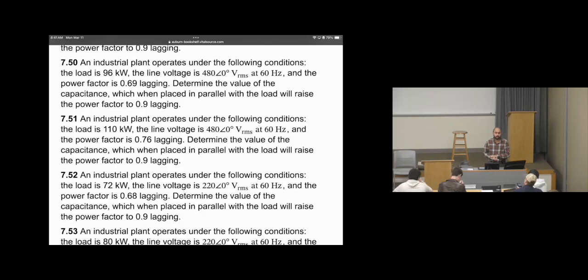These inductors consume a lot of reactive power. Their behavior will cause a lagging power factor. Here the lagging power factor is 76%. A 76% lagging power factor is poor. This will impact the power utility generation.